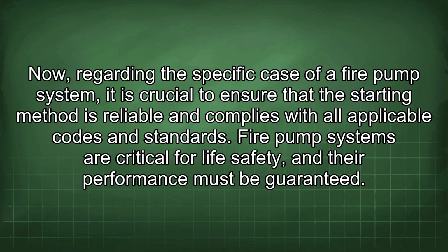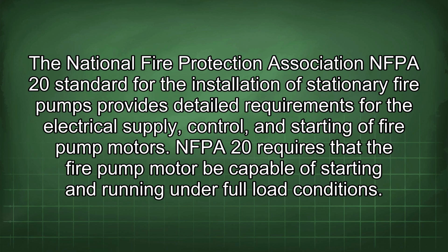Now, regarding the specific case of a fire pump system, it is crucial to ensure that the starting method is reliable and complies with all applicable codes and standards. Fire pump systems are critical for life safety, and their performance must be guaranteed. The National Fire Protection Association NFPA 20 standard for the installation of stationary fire pumps provides detailed requirements for the electrical supply, control, and starting of fire pump motors.